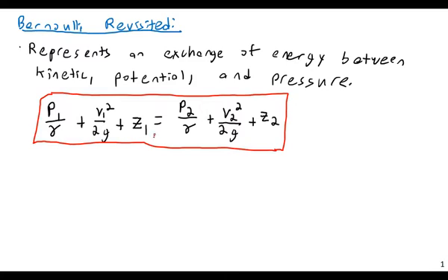Someone asked me a question over the weekend, which is, what is pressure head? Pressure head fundamentally is the pressure in a system expressed as a height, in feet or meters, or any other kind of height. Just as we discussed previously, we can conceptualize pressure as the ability of a gas at that pressure to raise a column of liquid, either water, mercury, etc., to a certain height. That is just a different way of expressing pressure.